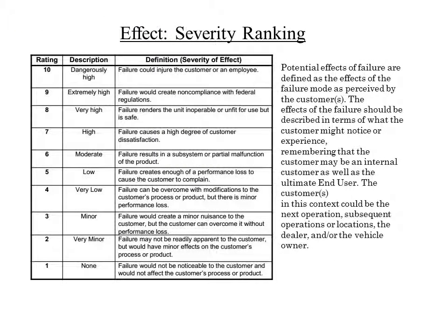How to quantify the impact of a failure mode. Severity is the value associated with the most serious effect for a given failure mode. Severity is a relative ranking within the scope of the individual FMEA. The team should agree on evaluation criteria and a ranking system and apply them consistently, even if modified for individual process analysis. It is not recommended to modify criteria ranking values of 9 and 10. Failure modes with a rank of severity 1 should not be analyzed further.